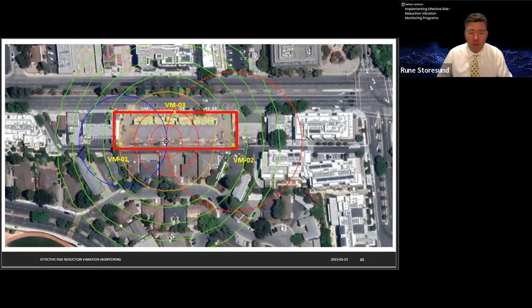This slide shows the vibration attenuation from event B now radiating out from the back calculated source location. As you can see, this hypothetical event also has more impact in the residential area than desired. So receiving this sort of automated alert is much more meaningful and helpful for interactive risk reduction than an arbitrary PPV reading at some monitor location. What we really care about is the PPV propagating from the source, not an isolated PPV reading at an instrument location.